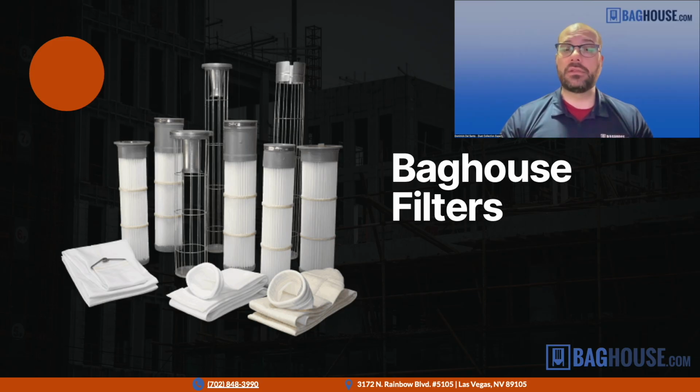And then in certain cases, if the temperature is above 400, which is about the limit of most aramid medias, then we might go up to something like fiberglass bags, which are more delicate. So we have to take some extra precautions if we use fiberglass bags. For example, we have to use special cages that have extra wires on them for fiberglass. But these could be used on some dryers and kiln applications. We'll have to take some extra precautions.